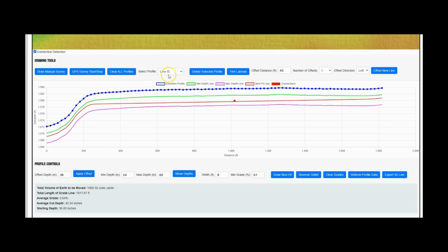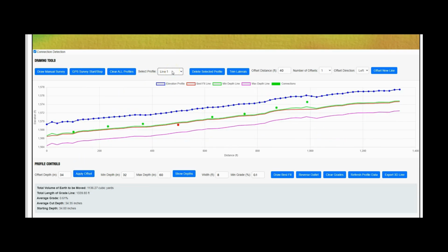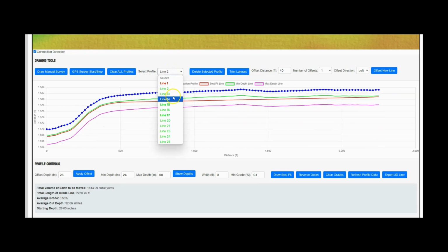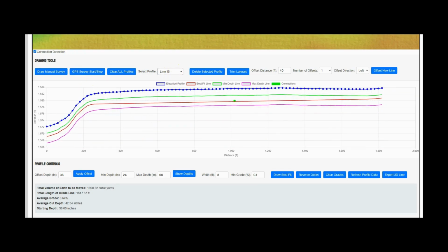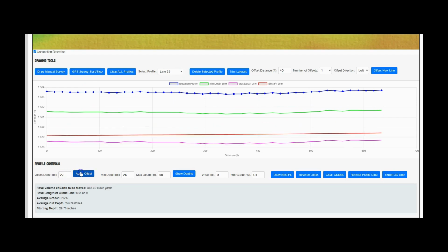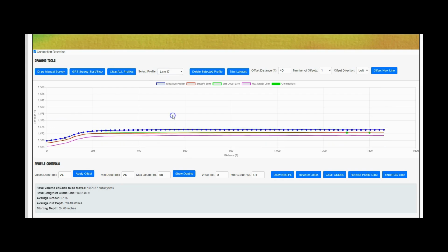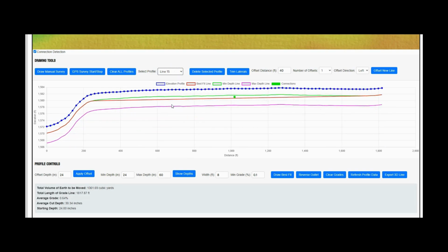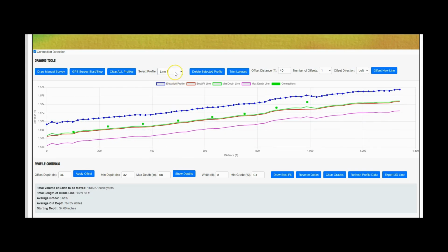In this example, we could try making the submain deeper to fit the lateral, but that would make the connection to the main too deep. The better solution is to reduce the depth of the lateral, say from 24 inches to around 22. It's not ideal, but it's a safer option than over-deepening mains and submains.